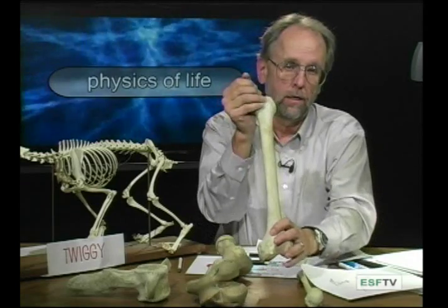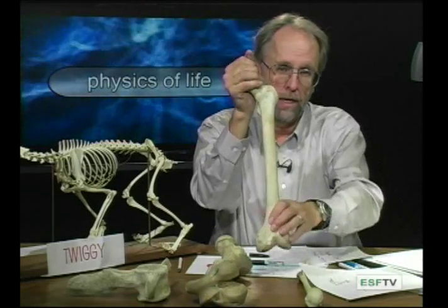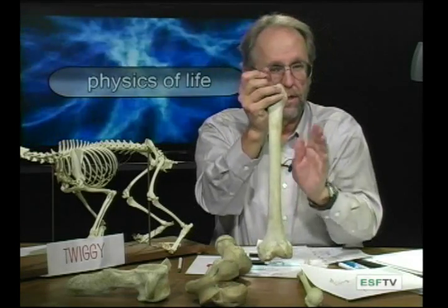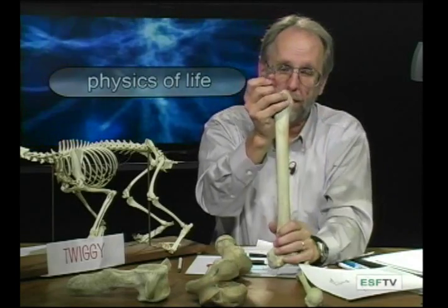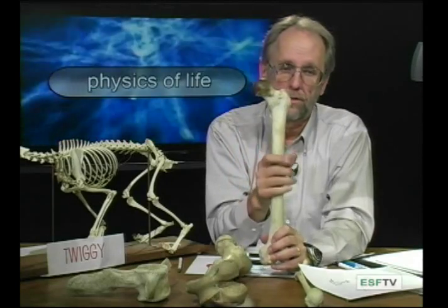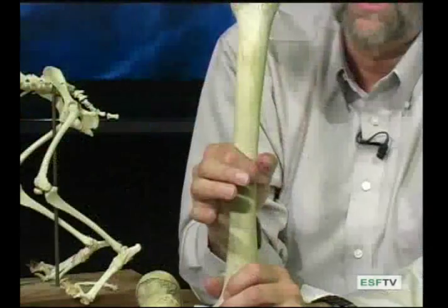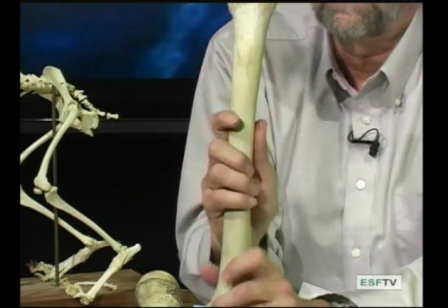And so, for example, if we look at the way the femur sits in our own body, this is the left femur here, then when the person is walking forward, the main direction of movement and the main direction of bending is going to be in this plane right here. But if you're running and you suddenly change direction, you're going to be experiencing a stress in the bone that's going to be going this way. The point is that the stresses and strains experienced by a femur can come from any direction. And the best design for a bone in that instance is to have a circular cross-section, something that can resist flexural deformation equally with strains coming from all sides.